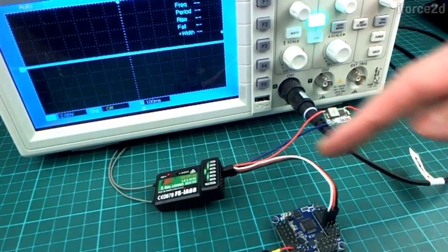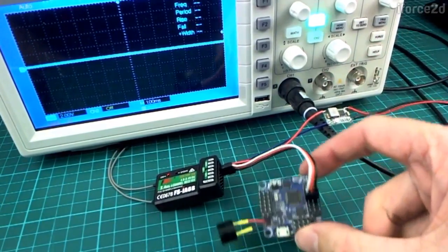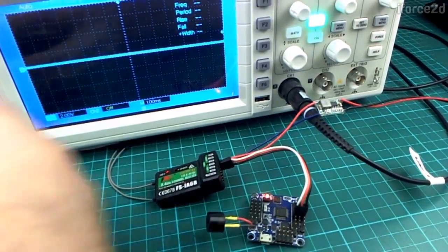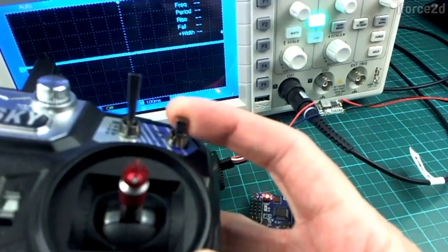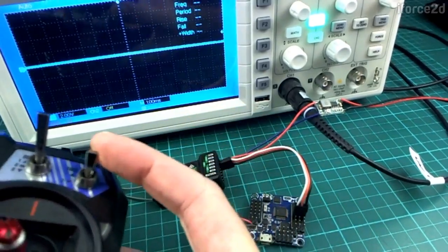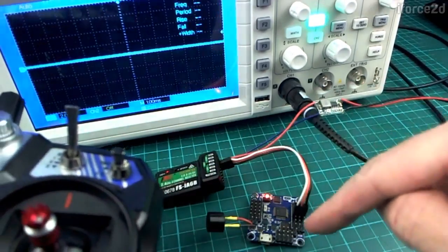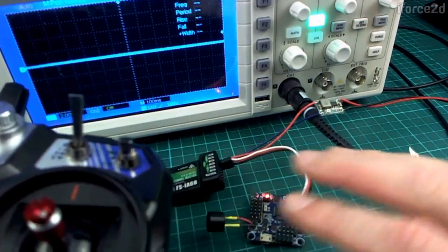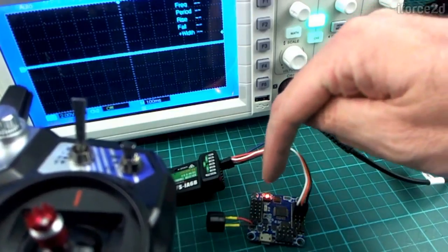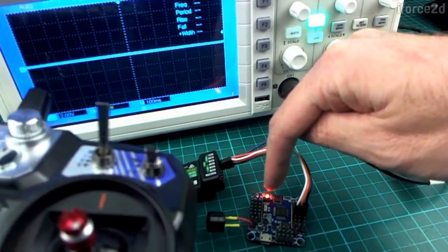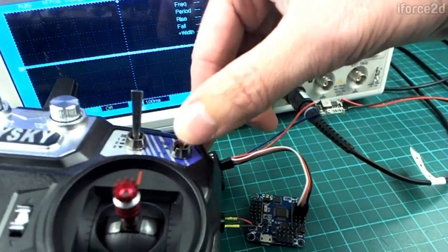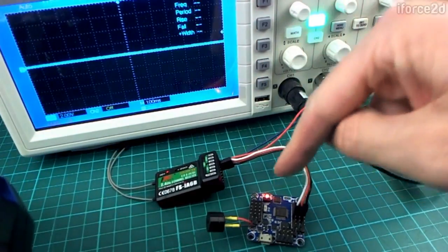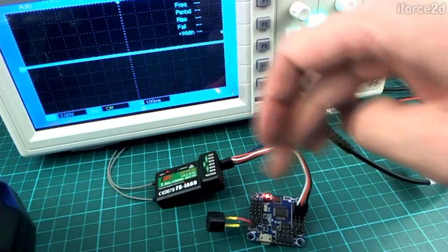Oops. And because we've got power coming through there, that will be a nice convenient way to power the flight controller for us too. And if I switch this other switch, you'll see that the receiver is sending this information about the switch position through to the flight controller, and at the moment it's set up to change a flight mode, which also happens to change one of those LEDs. So you can see the red LED is on there, and when I flip it like that, it beeps and it turns it off. So the flight controller is able to read this kind of PWM signal.